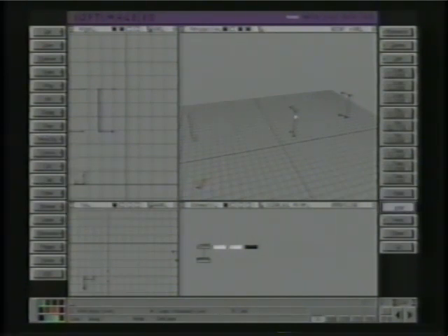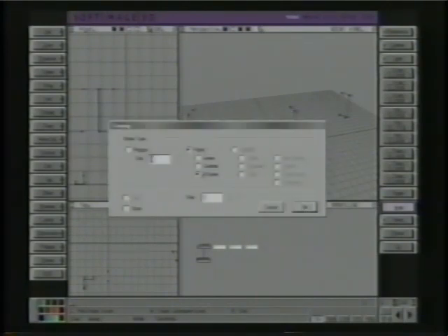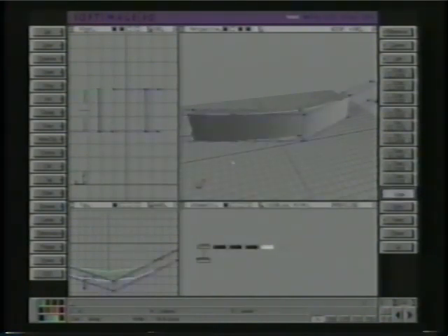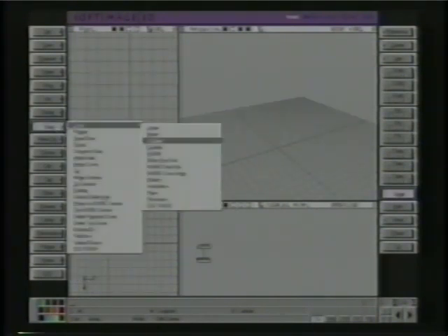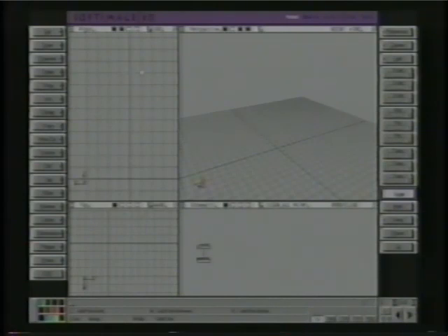So, surface, skin again. Like this, like this. Right click and choose B-spline maybe, or cardinal, and you can get a surface like this. B-splines are the most generic vanilla format in Softimage. They're in many ways the safest format. You can always convert up to NURBS, but you can't go back to B-splines.